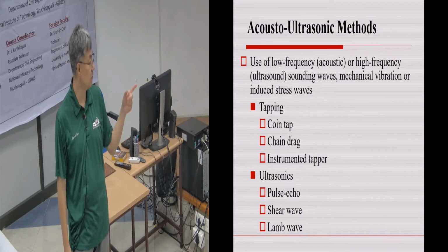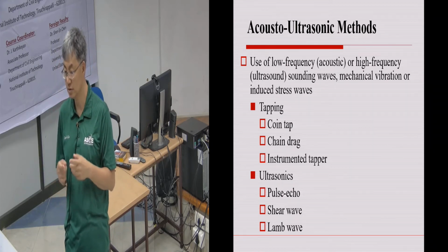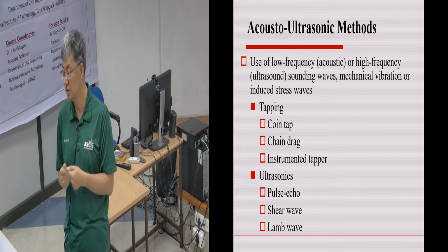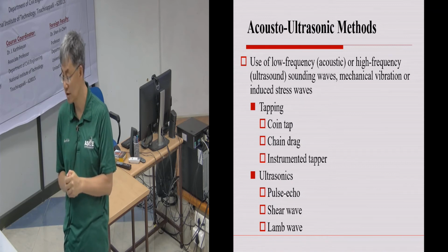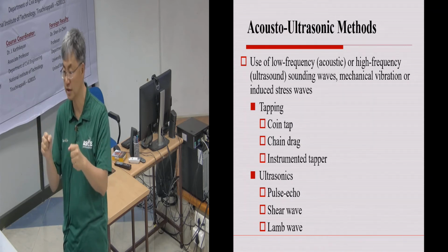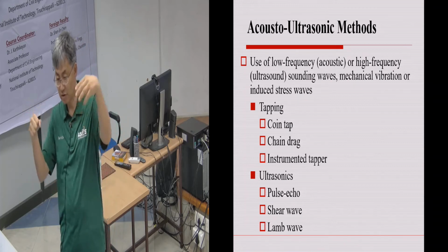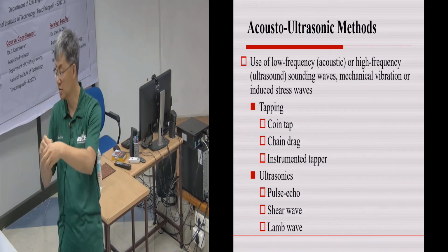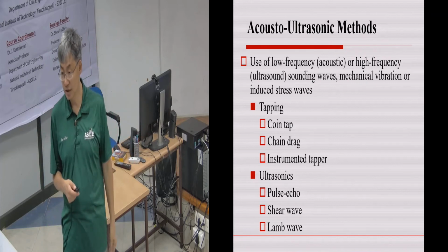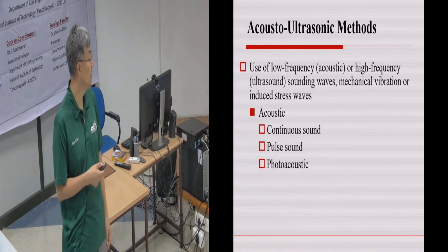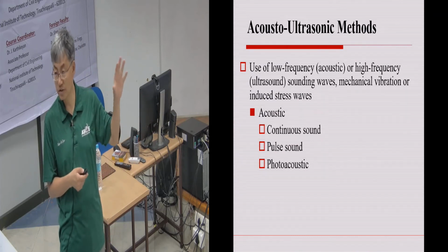And then ultrasound requires a higher level of understanding. The technician or the people who apply the technique need a high understanding of the limitations of the technique, especially the guided wave technique, such as pulse echo, where you need to be able to tell what direction the wave is propagating and so forth. So those require certified inspectors.